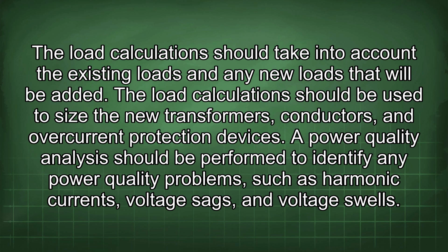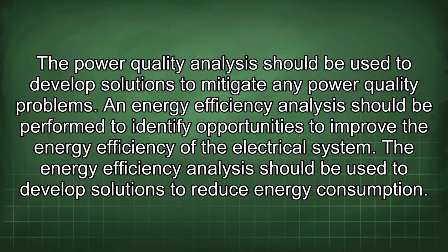A power quality analysis should be performed to identify any power quality problems such as harmonic currents, voltage sags, and voltage swells. The power quality analysis should be used to develop solutions to mitigate any power quality problems. An energy efficiency analysis should be performed to identify opportunities to improve the energy efficiency of the electrical system. The energy efficiency analysis should be used to develop solutions to reduce energy consumption.